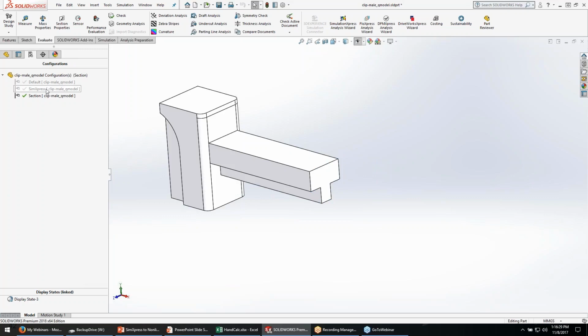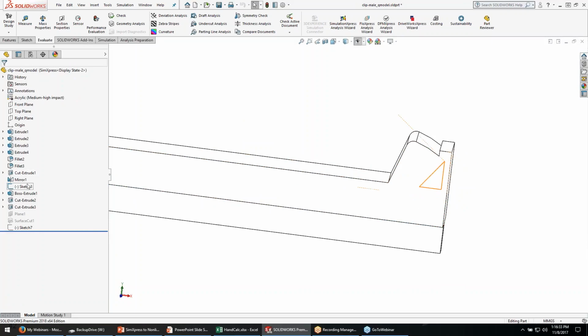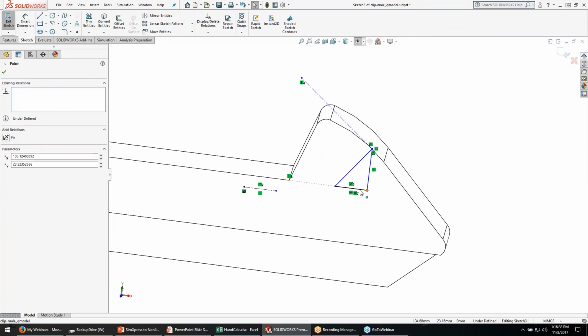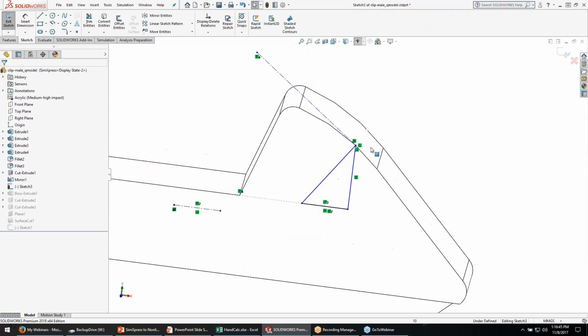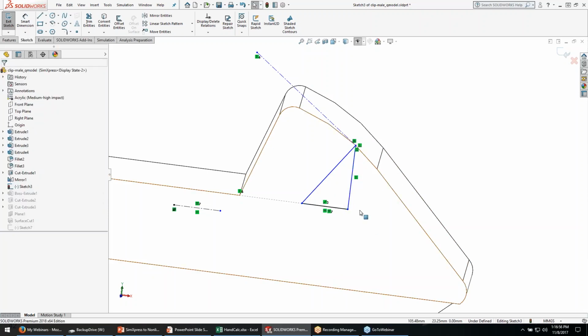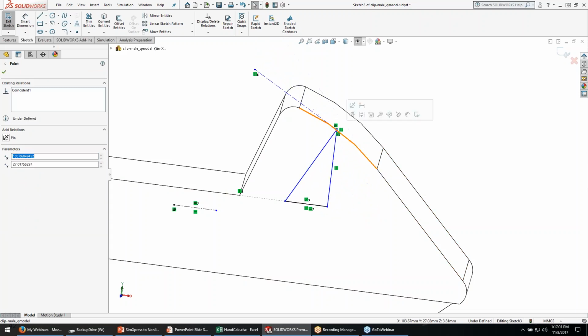Also, another thing I want to figure out is when I apply that load, the maximum horizontal force is going to be dependent on this triangle here that I've sketched in. So I'm assuming the contact force is going to be perpendicular to the surface. And you can see I've broken that contact force up into two components. A vertical component, which I'm assuming is linearly proportional to how far up I'm moving, how far down I'm bending this thing essentially.